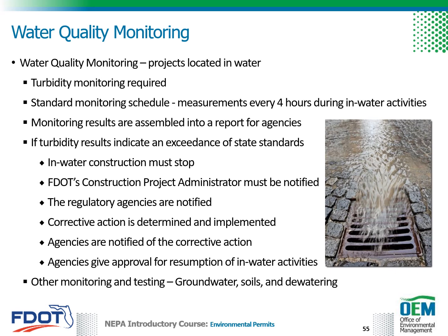In-water construction must stop. FDOT's construction project administrator must be notified. The regulatory agencies are notified by the contractor. Corrective action is determined and implemented, and agencies are notified of the corrective action, and agencies give approval for resumption of in-water activities.